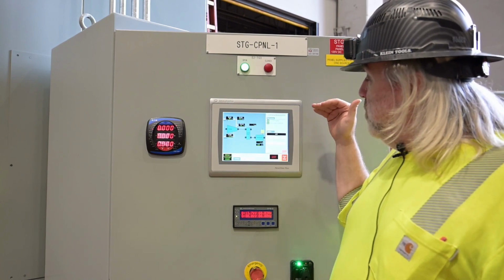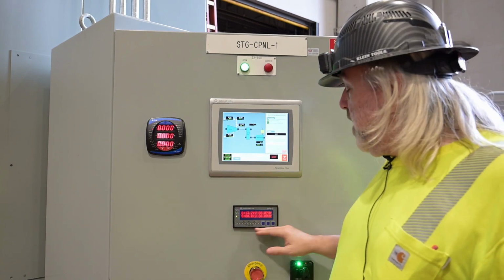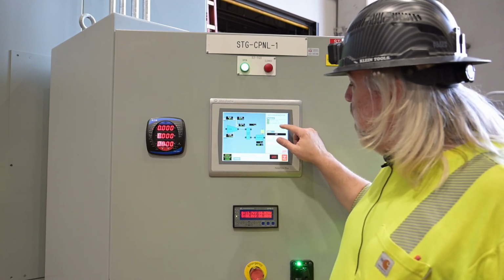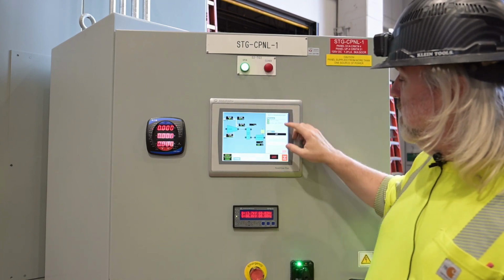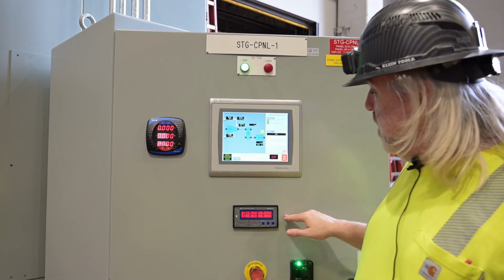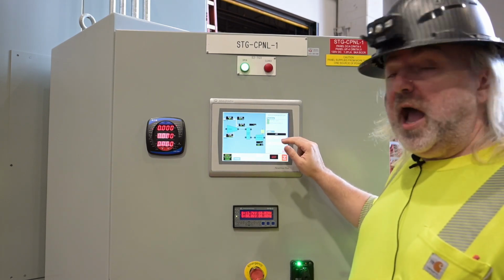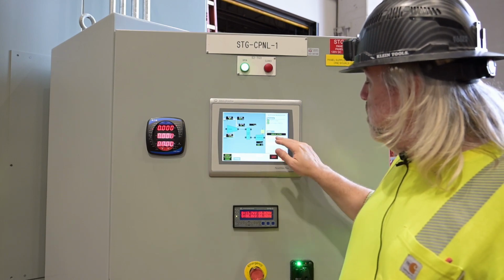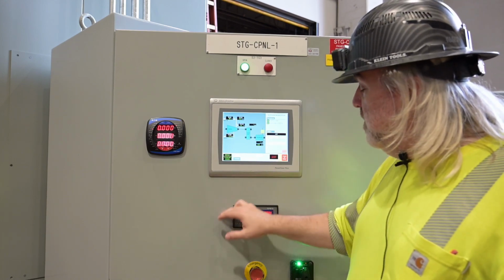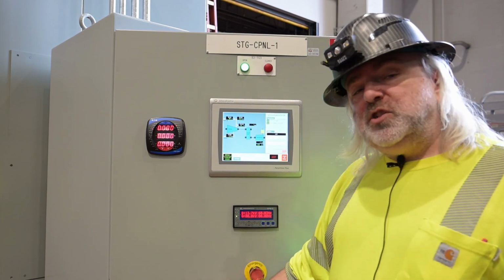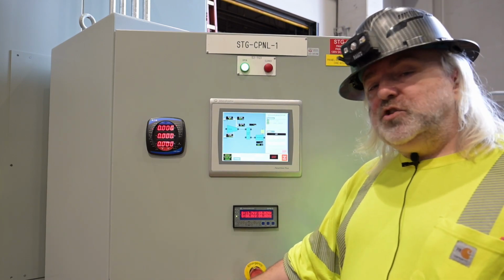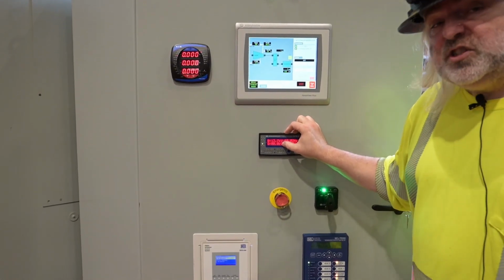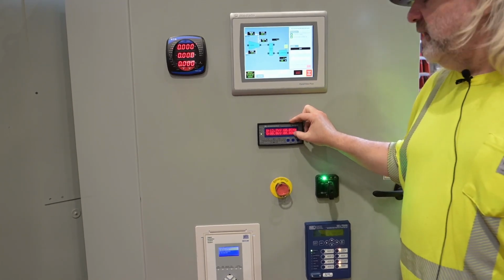Auto sync. Once you're at rated speed and the generator's excited, you can then enable your synchronization. To do that, we can come to this screen, verify our permissives, breaker is open, and the synchronizer is okay. If both those things are true, then we can synchronize. To synchronize, we'll either select auto or manual. If you select auto, this device and this device will adjust frequency and voltage to accommodate your necessary generator voltage slightly higher, generator frequency slightly higher.